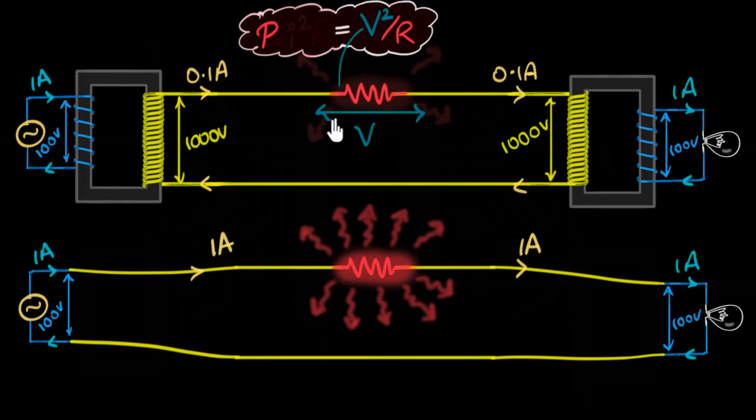And so, yeah, because there is some voltage drop happening, not all the 1000 volts will appear over here. Some of the voltage drop will appear over here, but that amount is much smaller than what you would get here. A lot of that 100 volt would get appeared over here. Does that make sense? So even voltage wise, if you look at it, power dissipated has reduced. Stepping up voltage helps in efficient power transfer.